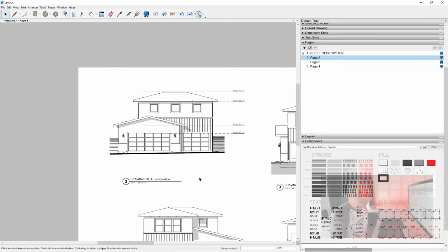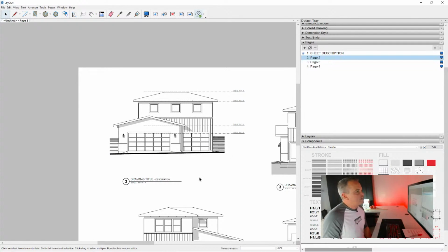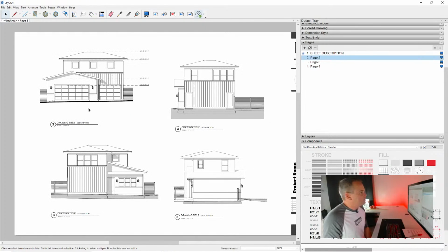All right, so that is how I get these elevations all buttoned up and kind of give a nice clean look so that they have a heavy base plane or ground plane, and kind of trim them up. And I will say that if you were very aggressively modifying the site and the ground plane, then hold back on doing this until later. But usually when you start shooting your elevations, you can confidently move forward with this and then start working in the annotations. So cool.